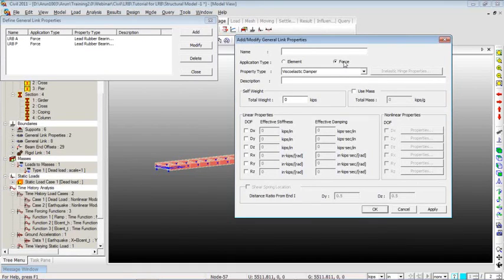So you can go to the contractor or the manufacturer of such bearing pads, get these numbers, punch them in, and based on those nonlinear properties the program will calculate what forces are coming into that lead rubber bearing pad, and how these forces will be transferred from the superstructure to substructure, or from substructure to the superstructure, based on different planes. Just as I mentioned, for lead rubber bearing pads, in the global XY direction of the plane the shear is coupled, whereas other degrees of freedom are basically linearly independent. So you need to choose your parameters and the degrees of freedom accordingly when you're modeling that type of seismic isolator.